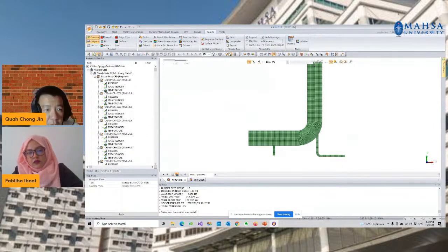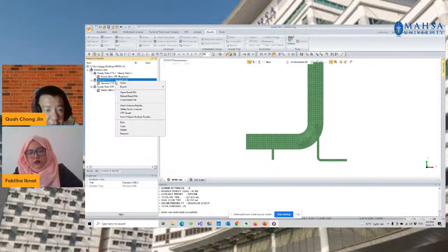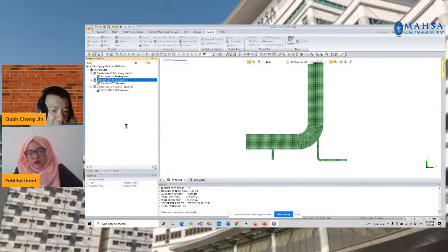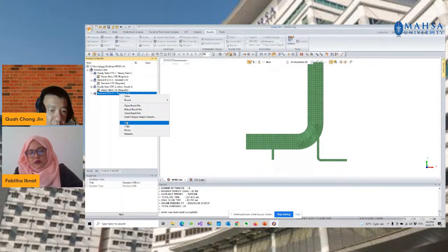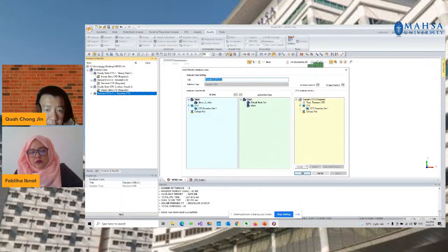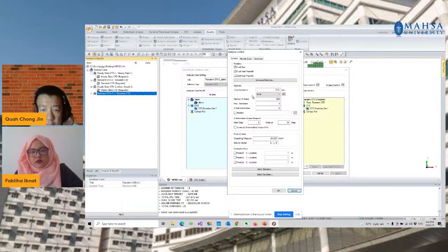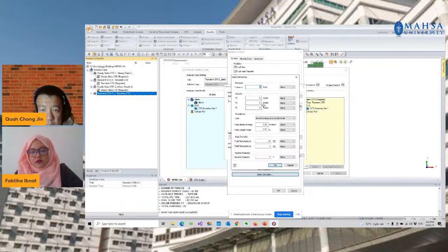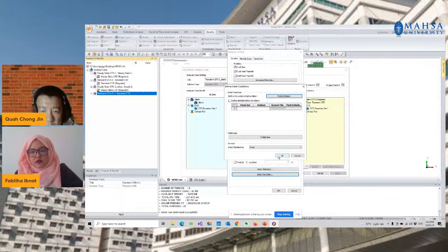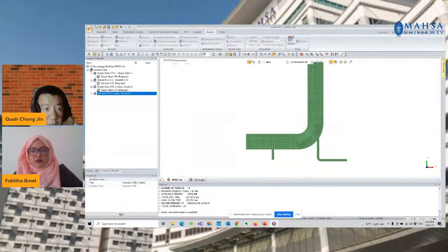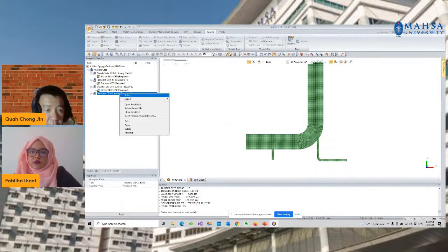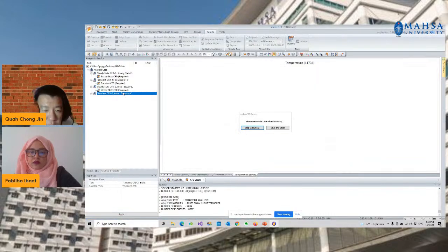Okay, so what I'm going to do is copy the previous case study, like what I did for the steady state, and go to edits, saying that this has two inlets. For example, make sure that I have selected the right mesh, that the fluid is there, and that the initial condition has been set up accordingly. Then I should be able to run a transient simulation.